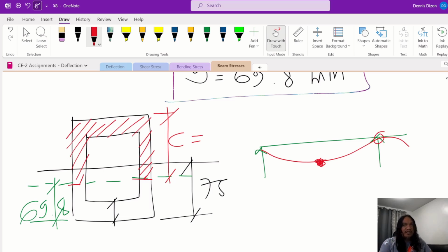That's why we have to provide steel reinforcement at the weak portion of the concrete, which is the one below the neutral axis in positive moment. That's why at midspan, our rebars for concrete are always at the bottom.